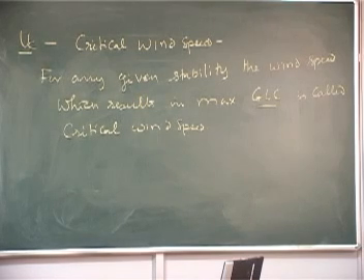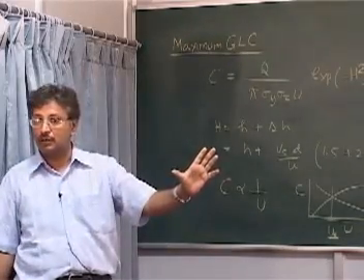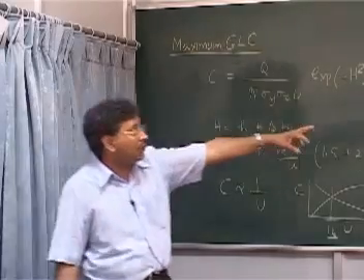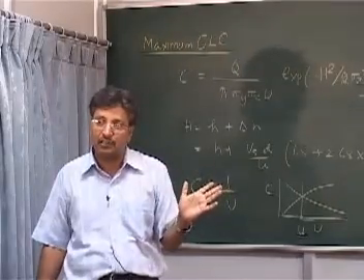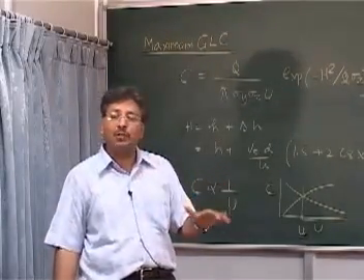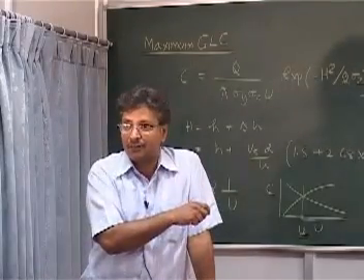So suppose you are planning a power plant or a refinery or a sulfuric acid plant, then you want to say, well, what will be the maximum concentration under any given conditions. As somebody said, you don't even know what is going to happen the next hour, but if you can find out the critical condition, okay, this is almost like predicting the global ever maximum concentration, because this is not based on the measurement. U critical, is it based on measurement? It's not based on the measurement, right. You can find out the critical wind speed whether the condition may occur or may not occur, okay.